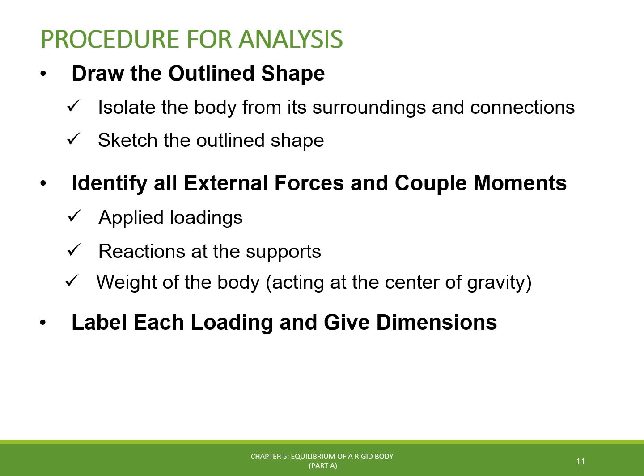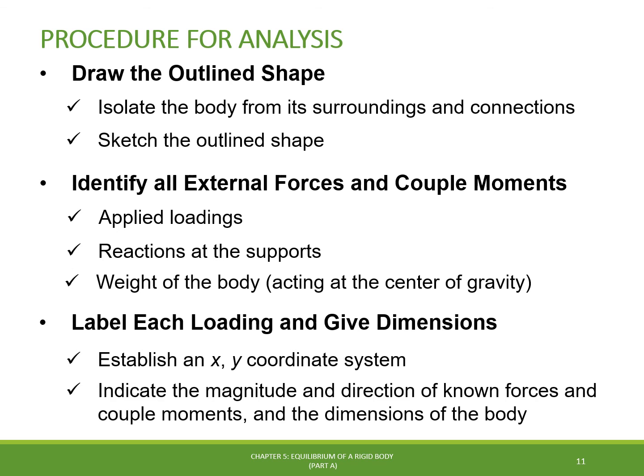Lastly, we have to label each loading and give the appropriate dimensions by first establishing the direction of the coordinate system axes and then labeling the magnitude and directions of the known forces and couple moments, and the dimensions given to calculate the moment of forces. For the unknown forces and couple moments, we have to use letters to represent their magnitudes and direction angles, in which initially we are free to assume their direction and check them after the calculations are done.